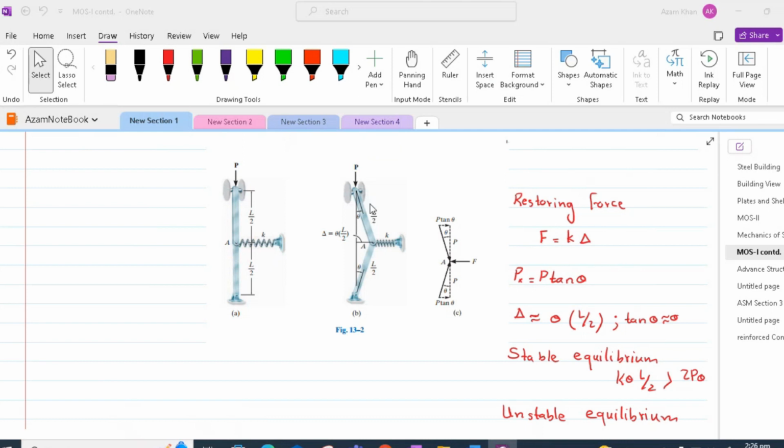As we can see, the top bar has bent by an angle theta, or in other words has deflected by an angle theta. So obviously there is a proportion of the load P running in the top bar. The remaining load will induce horizontal buckling.